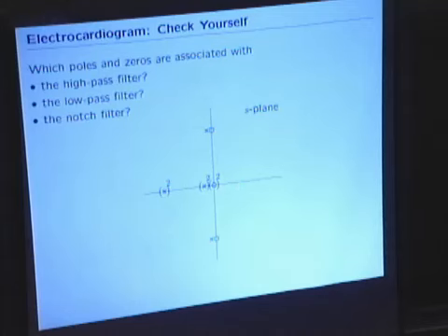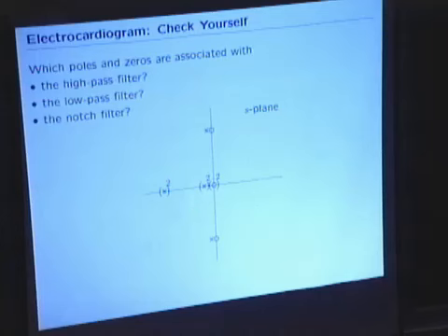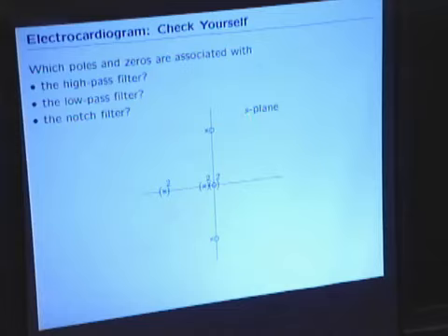What are the poles for? They flatten it out. So if you think about reading off the effect of the poles and zeros, starting at zero and going to bigger and bigger radiuses, then the first thing you have to worry about going left to right on the Bode plot is the zeros doing this, and then these poles flatten out the zeros. So what's this doing? That's the thing that's attenuating the high frequencies, which leaves us with this. What's that? And how do you know it's a notch?